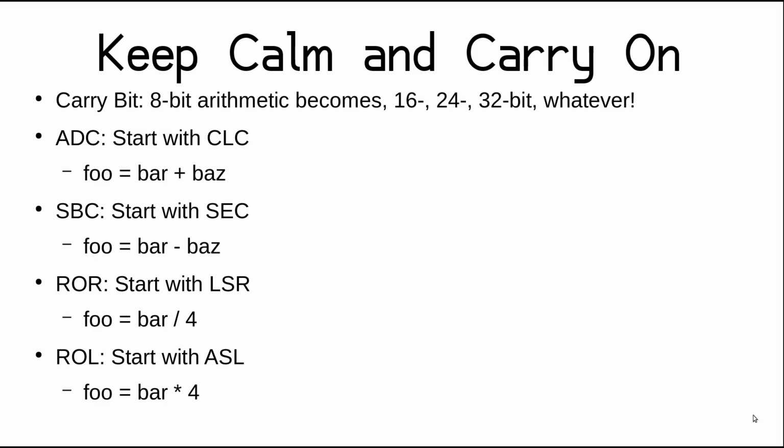The carry bit is the main linkage between the different bytes in a value when doing any math operation. It lets us do math at widths of any multiple of 8-bit, as allowed by available RAM. With the X16, we have more than enough RAM to do 256-bit math for a pretty large data set, but chances are that's not what you are trying to do. A humble Raspberry Pi will absolutely smoke the X16 when it comes to complex math. So the reality is you probably just need to go up to 32-bit values for any application. And even then, needing to go beyond 16 bits is pretty rare.